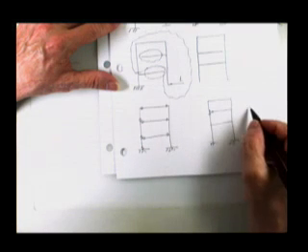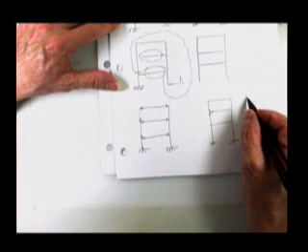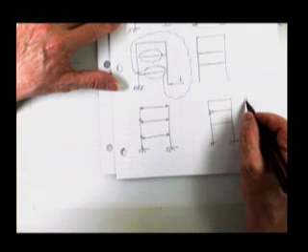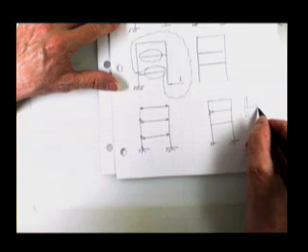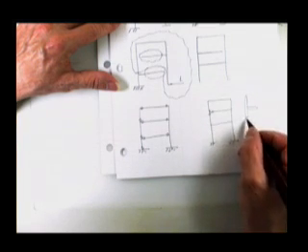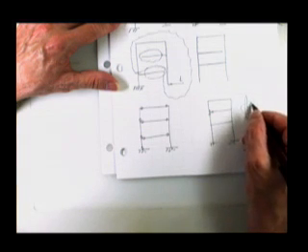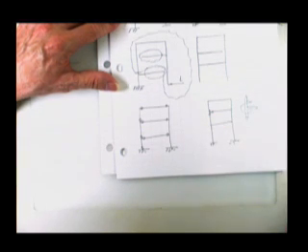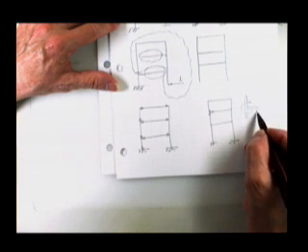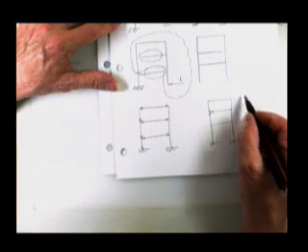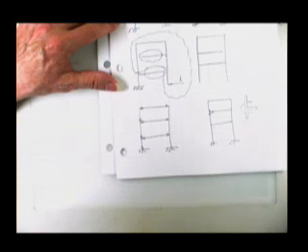But the problem is this little piece right at the corner itself, where you put the pins, it does not hold up by itself. Any moment that was applied to that joint would not have any resisting moment to pull that moment back out. And therefore, it would be unacceptable for a primary or for a real structure.